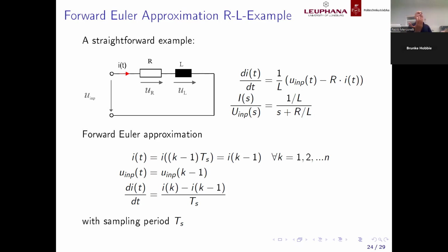In electrotechnics, we have seen this many times. In discrete form, the phase delay is a delay in time. This means that if you have an integral, it is delayed in accordance with the sample time Ts which I use. Now, roughly speaking, this is really intuitive. In fact, at least I would like to say, using this forward Euler approximation, because if you use the backward approximation, it is something different.